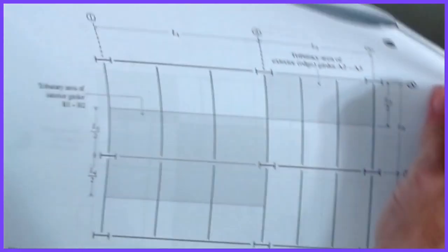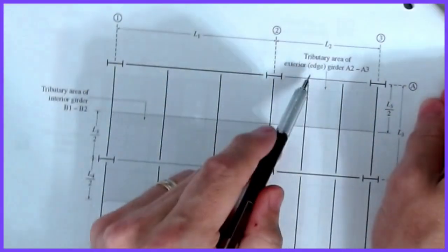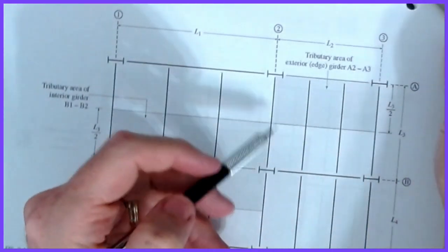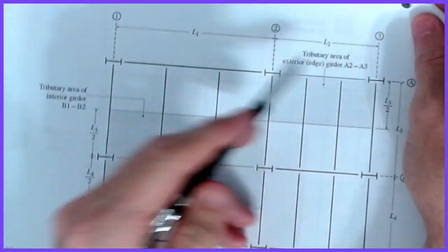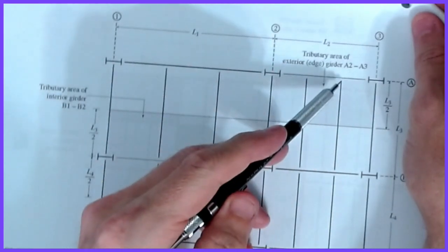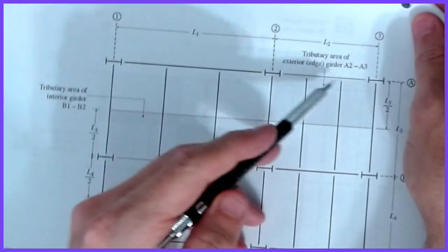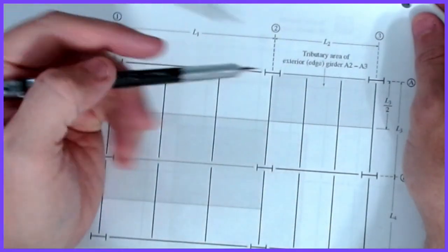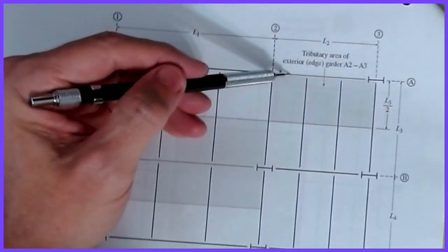Okay, all right. But let's go take a look at the girders. So we've got an edge girder happening here. He's holding up these beams here and here. Now one way that we could do that is the exact method that I showed you, where you went through and put point loads on the girder, or we could get a rough feel for how much load is on this by taking the tributary area associated with the girder.